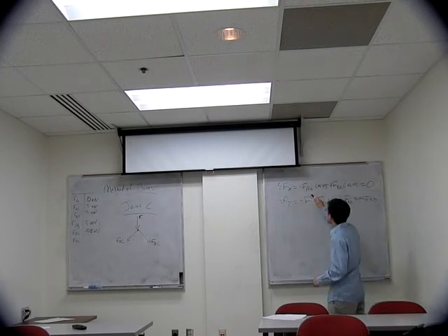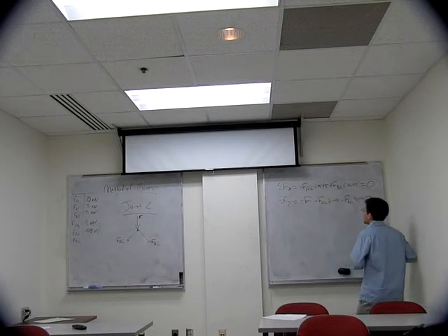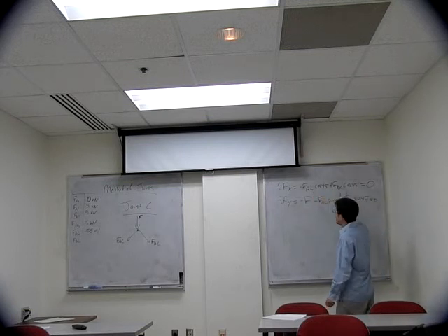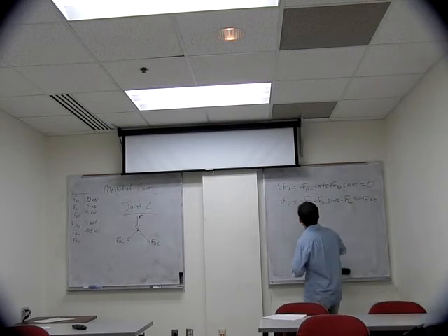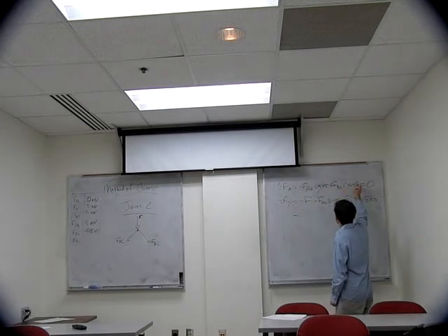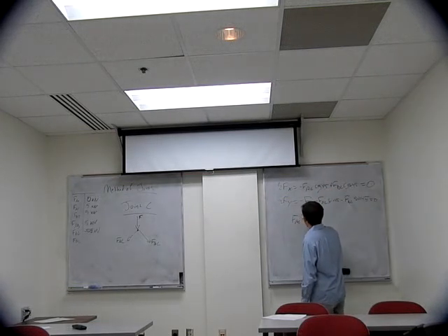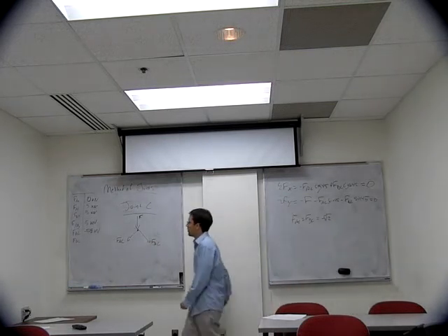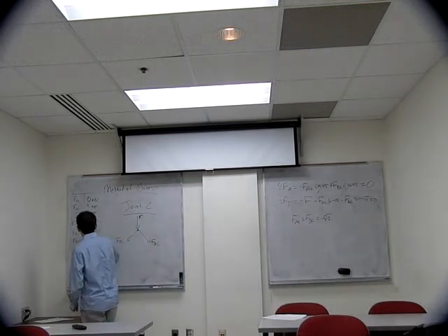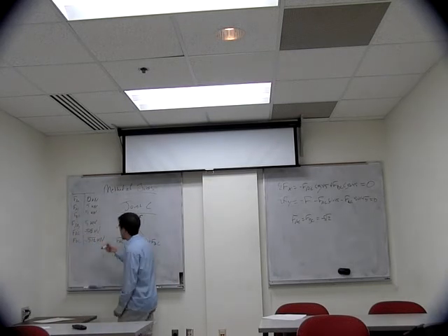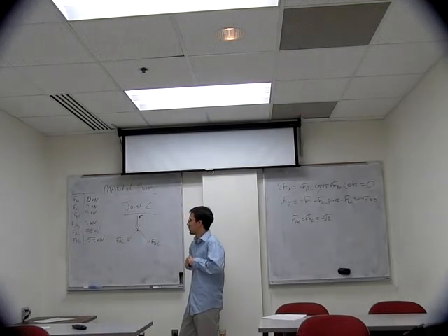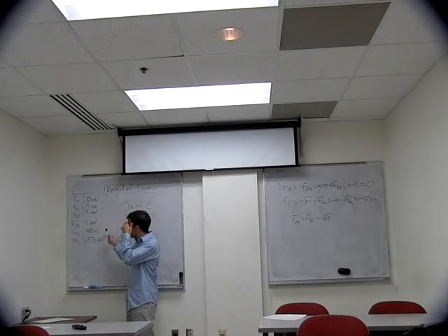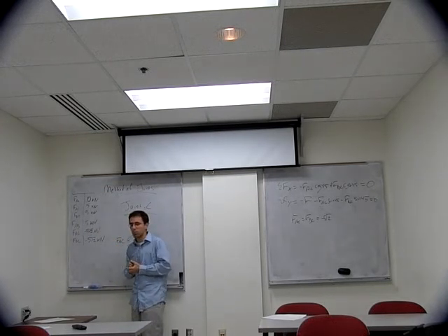All right. So first, let's look at the summation in x. Since we already know FAC, we want to find FBC. So here we can actually just solve. You can see that the cosines of 45 cancel. So FAC is just equal to FBC, which is equal to negative 5 times the square root of 2. And you come back over here, and we see that we actually have all of the parameters that we were looking for. We've solved for all of our reactive forces. We've solved for all of our member forces.